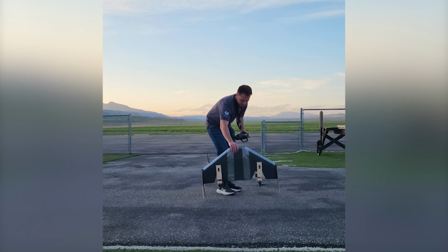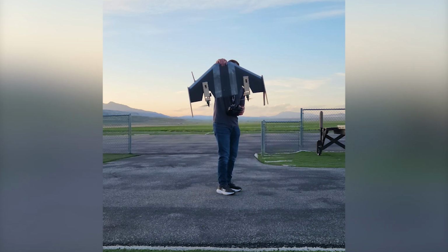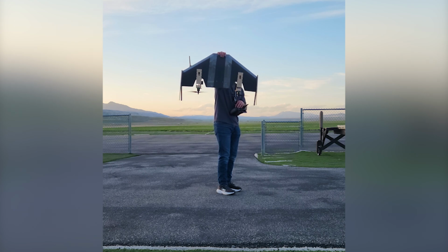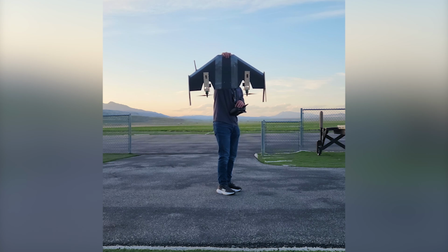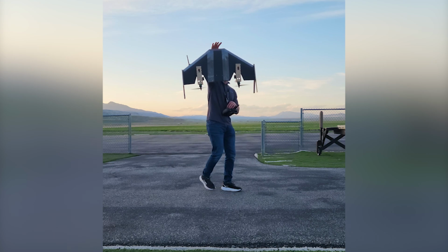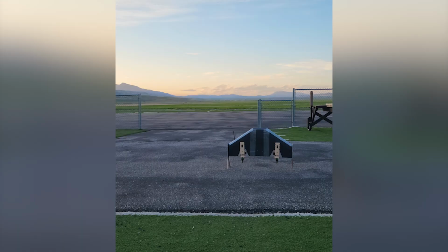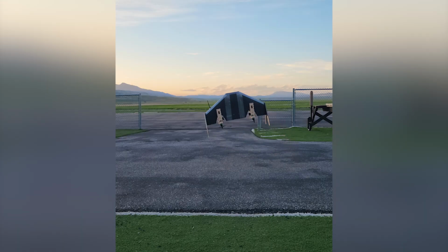Eventually I get pretty close to the vehicle operating on its own. The roll axis is the hardest to tune as it has the biggest moment arm. The weather lately hasn't been the easiest to tune with, specifically with the wind. You can see here that I don't have the roll angle quite dialed in yet, but despite this, I'm still able to command values to overcome this error.